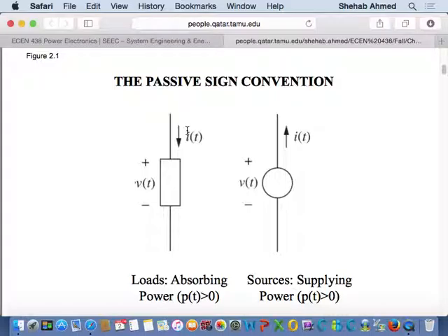So in that case, what is the motor doing? The motor was the load, right? It was consuming power. Current was coming into the motor, right? And batteries were doing what? Batteries were providing power to the motor, so that was the positive power, right? Now the motor is acting as a generator during the regenerative braking period.